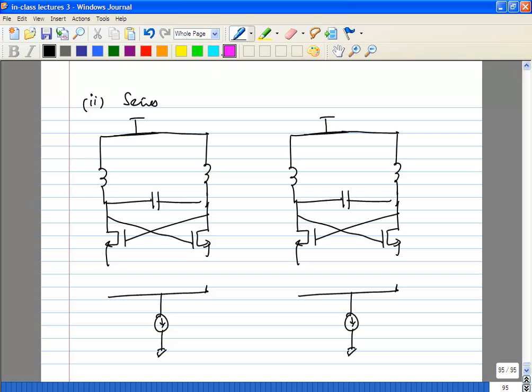That's okay. You can couple the oscillator outputs through series. Okay, and this series coupling, you can interchange the positions of the cross coupled transistors and the series transistors. That has been done also.